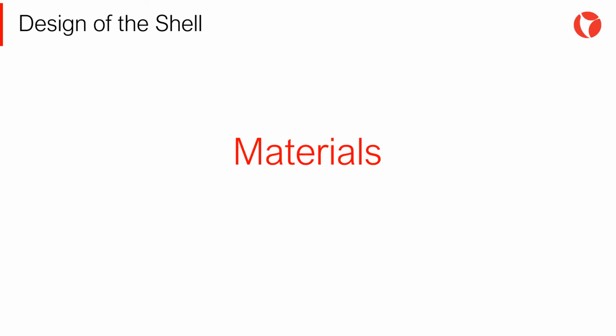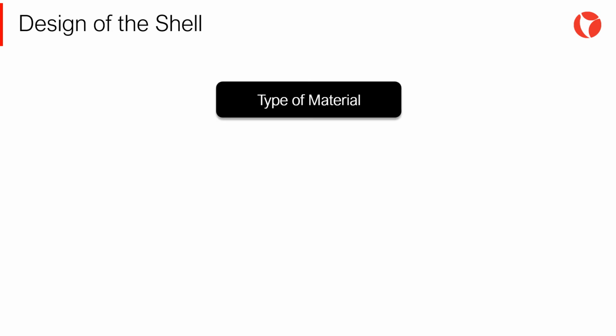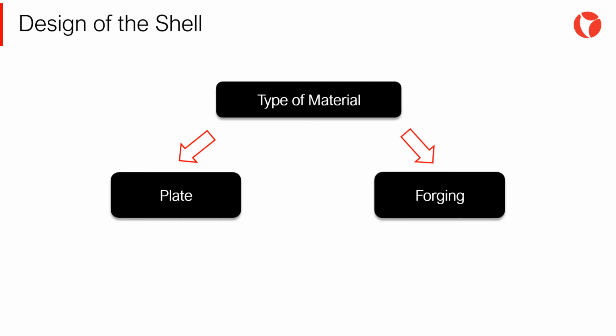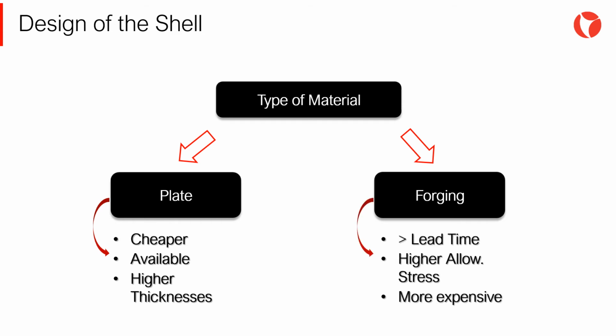As mentioned before, flat covers are generally tailored for each shell and tube heat exchanger instead of standard flanges. This element can be fabricated out of plates or out of forgings. While plate fabricated ones are less expensive and normally deliver thicker designs, forged ones generally have higher level stresses, requiring longer lead times though.